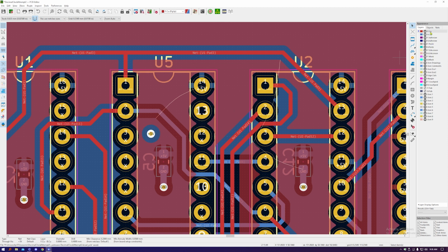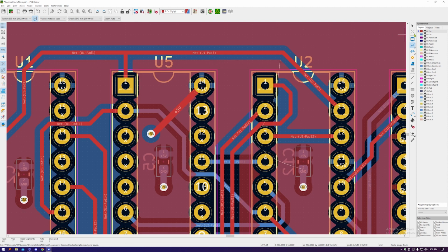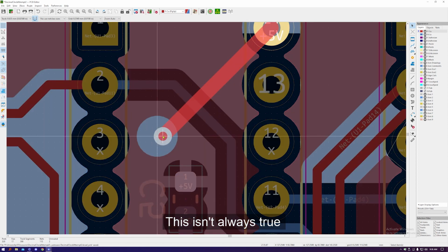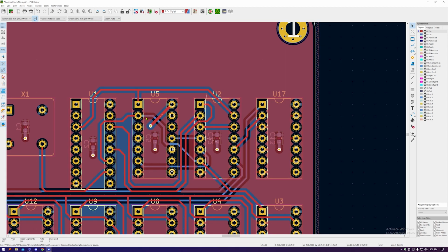There we go. Now on the red, because I can't use blue because there's a trace there, on the front we're going to go from that via up to here. It doesn't need to go to the pin, because you could use another via here, but I am going to take it to the pin because the fewer vias the better. I'm also going to move this via slightly so that the trace is nice and straight. There we go, fixed that one.